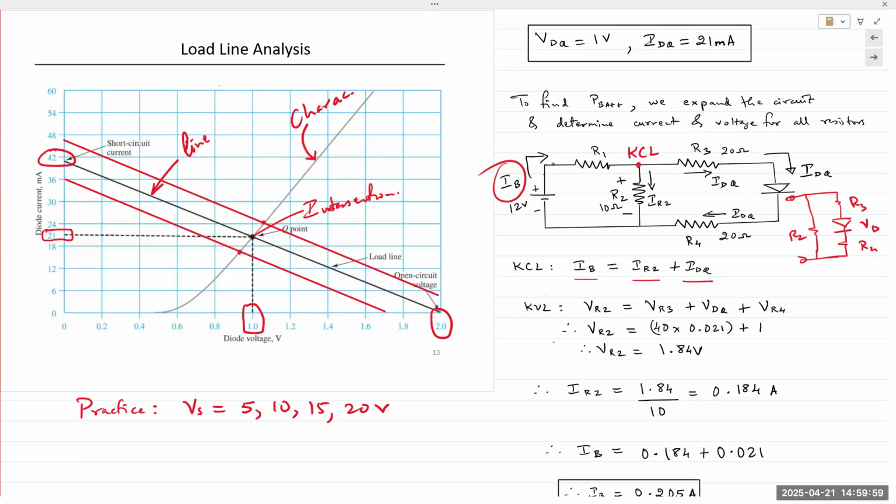R2 is in parallel with the 3 components on the far right. They share the exact same 2 nodes. When you take any 2 nodes in a circuit, anything connected between those 2 nodes will share the same voltage, because that voltage is a result of all of those components working together.